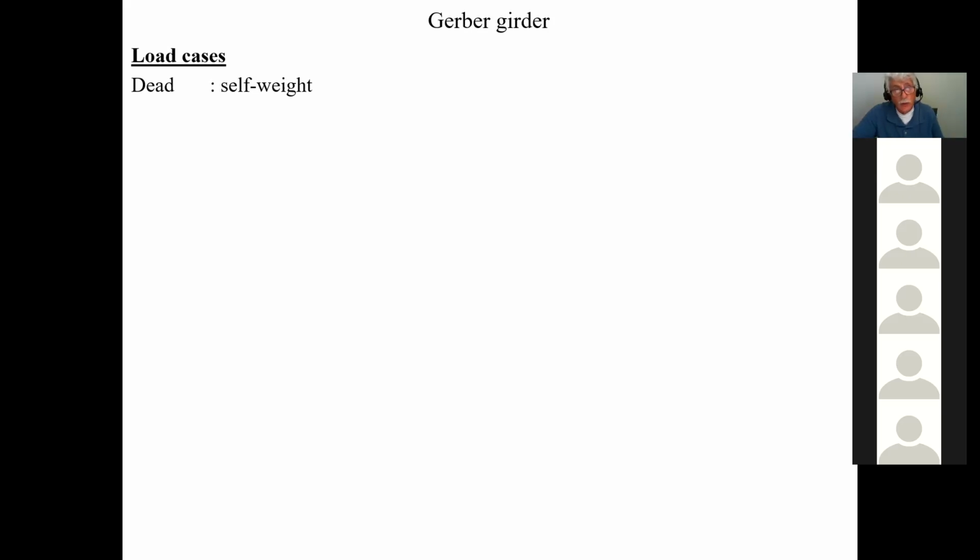Well, in real life, the dead load that we calculate that's being carried by the member, I call that superimposed dead load. It's a superimposed load on the member. You understand? And what I call that in ADA, I call that SID. So instead of changing dead to self-weight, just create another one called SID for the superimposed dead load. And that's your 1 kPa or whatever it is. That's what it really is. Do you agree?